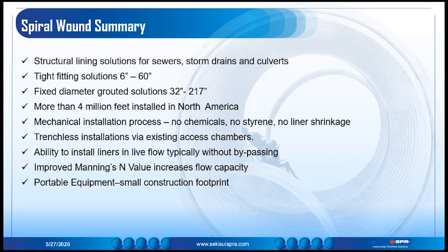All right, thank you, Jackie. Our next question is, Sekisui liners have a continuous spiral seam. What post-rehabilitation testing is done to verify the liners were installed correctly and that there will be no infiltration or root intrusion between the locks? Ryan, ASTM F1741 outlines the post-installation verification testing, including post-CCTV or manual entry. If required by an agency, leakage testing can be done. An air test will be performed per ASTM F1741 or an exfiltration test done per F1741-7.2.1. Neither test is recommended for pipelines greater than 36 inches.